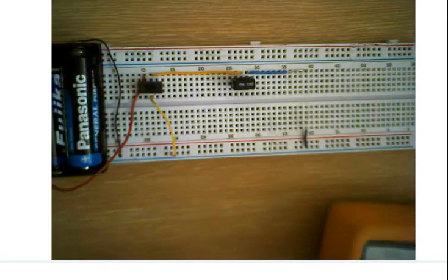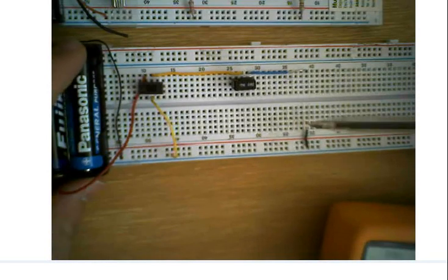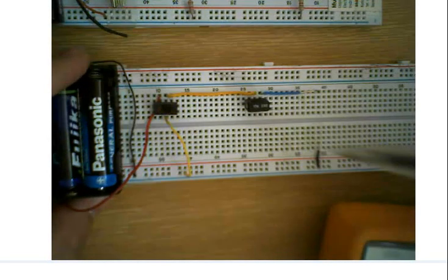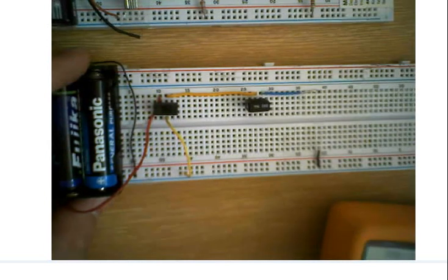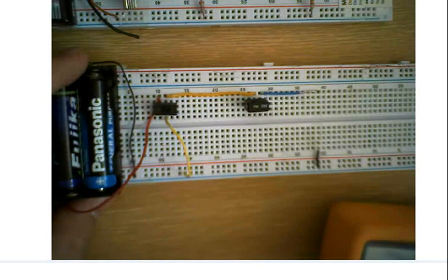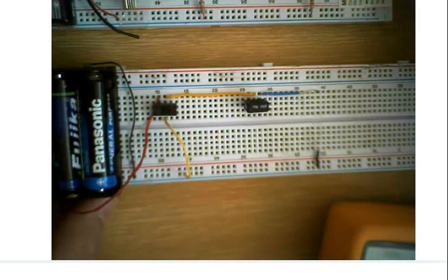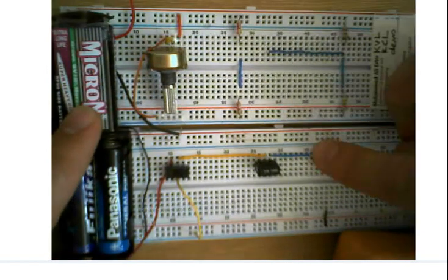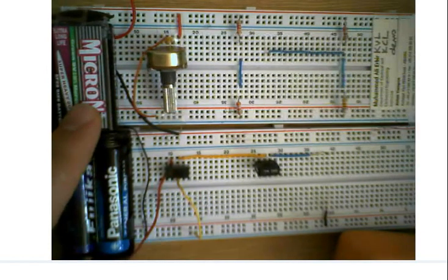So I have the same Thevenin voltage for that circuit. Okay, I have the same voltage, I have the same resistance. So this Thevenin circuit will be equal to my actual circuit. Now I can test. I will replace different resistors between points A and B in both circuits, and I will see the same values.